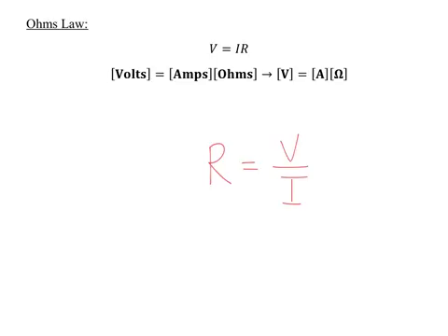So if you want to measure the resistance of any appliance, a microwave, an air conditioner, a light bulb, anything, you can measure the voltage and the current that are flowing. The current flows through it, and you would measure the difference in the voltage. Before the energy flows through the resistor, you're going to have some voltage. Afterward, you're going to have a different voltage. The difference in that voltage is what goes in for the numerator here. The amount of current flowing through the actual wire is going to be the same anywhere, so you can measure that current anywhere. You can measure the voltage drop, the potential difference, here. Divide these two and you'll get the resistance of that element.